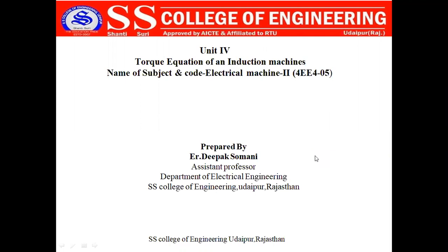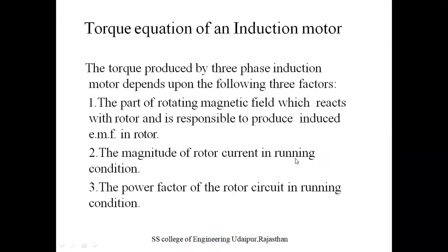Today I am going to cover the topic torque equation of an induction machine. The torque produced by a three-phase induction motor depends upon the following three factors: the rotor current, the power factor, and the rotating magnetic field, which is responsible to produce induced EMF in the rotor. The equation becomes